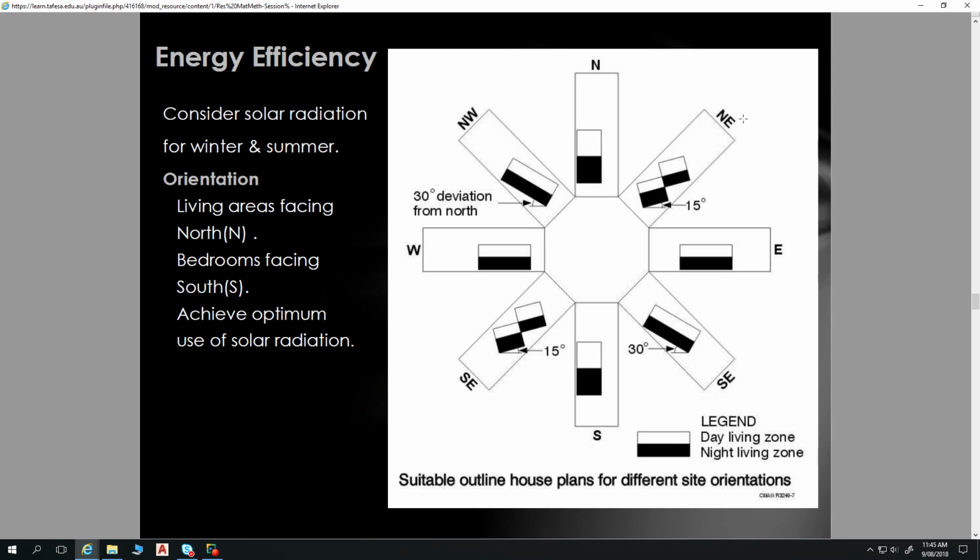One of the things that plays into that is orientation of the building, solar access. Do we have good access in terms of getting lots of sun in there during winter time, or do we have bad access in terms of getting sun in there in summertime, or sun directly from a westerly or easterly direction, providing excessive levels of heat when we don't want it?